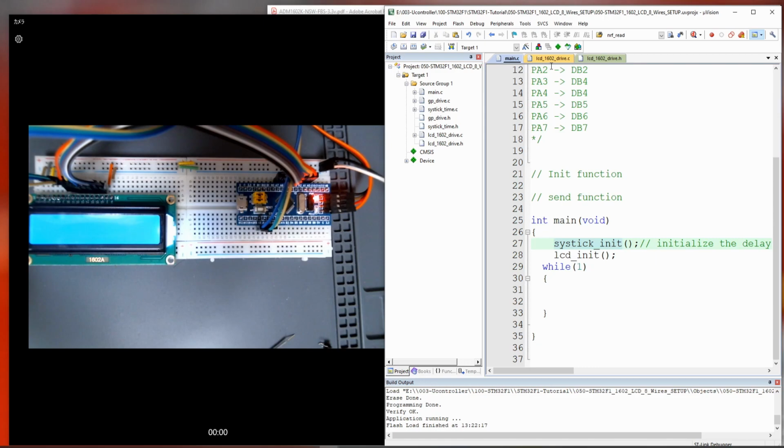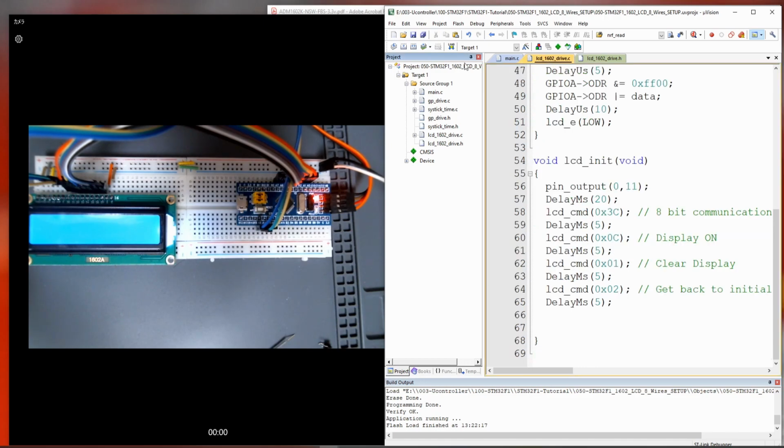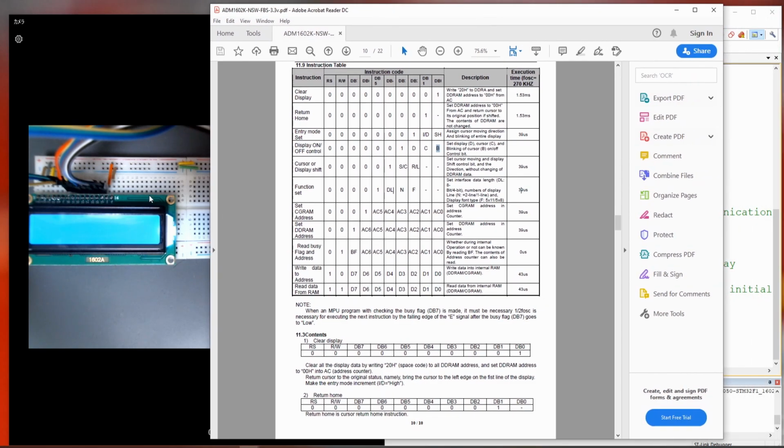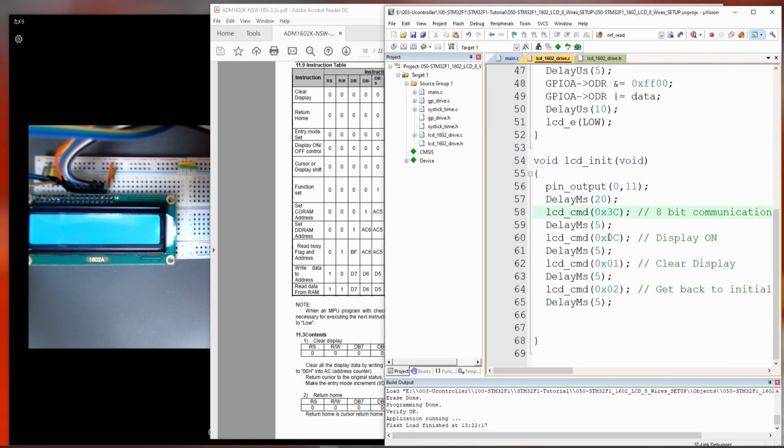Let's have something a little bit different. In this function, let me show you the cursor and the blinking. I will put the display on, not 0x0C, but F this time, and you will see how it changes. If I save, run, you see we do have a blinking cursor. Good, that's fantastic. So our init function is working. Let me come back here to C.